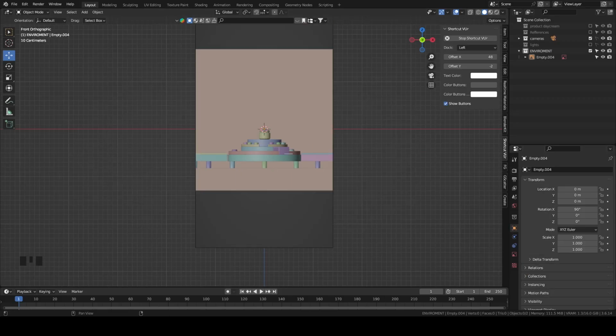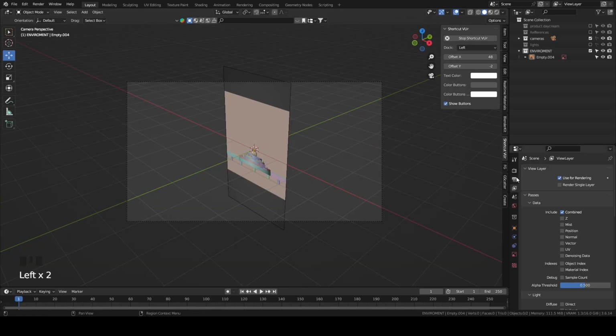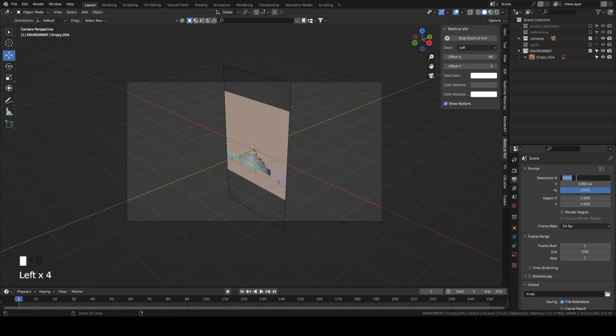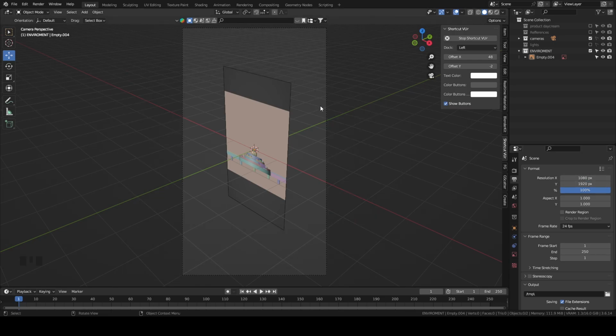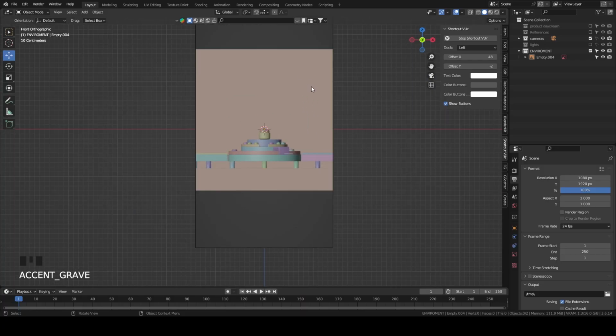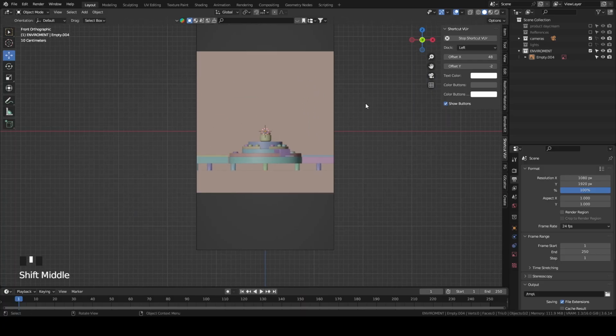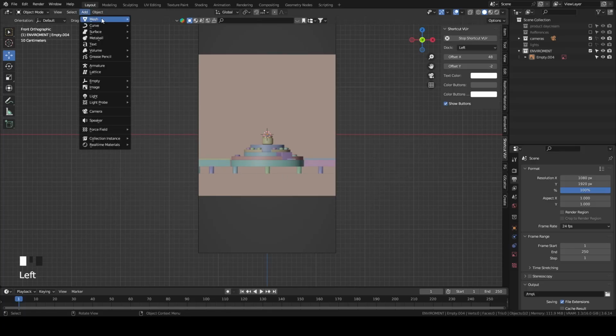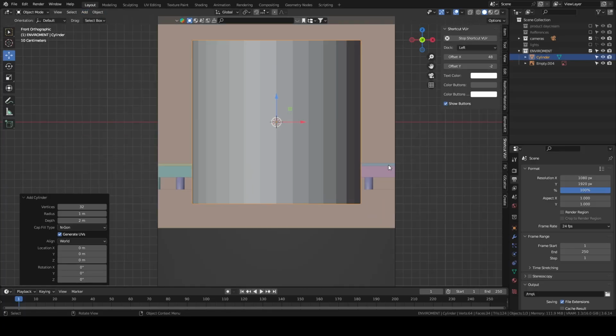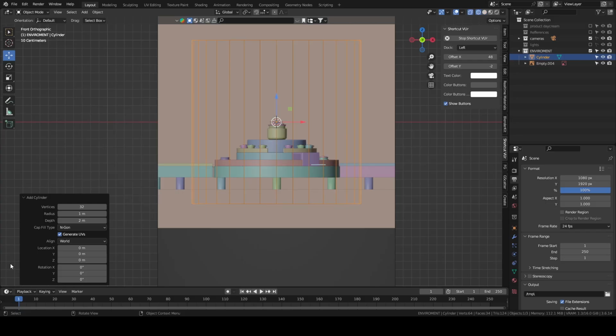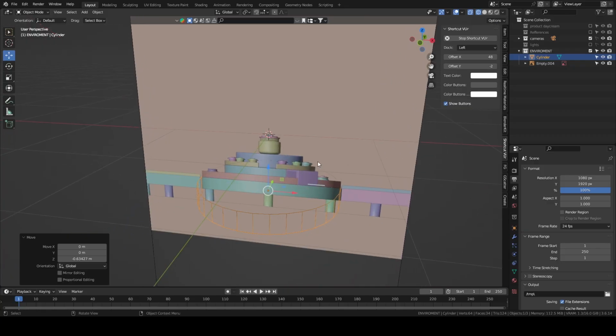So before I begin I would like to also change the camera settings around here. We're gonna have this twisted 1080 1920 basically for Instagram reels, and everything we're going to do about the environment is basically primitive objects, as you can see, cylindrical shapes. So let's start off with the cylinder. I'll make the radius a little bit smaller, also reduce the depth. Not that small though. I'm gonna use this as a basic reference and we'll see how it looks there.